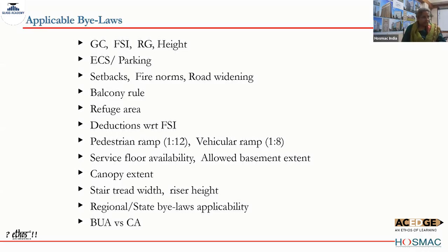But 3 meters is never good for a hospital because under the slab are, again, I would say this word, the nerves of the building, okay? Electrical lines, plumbing lines, firefighting, air conditioning ducting, and also the medical gas pipelines. All these are like a network under every slab. If a hospital has 3 slabs or 20 slabs, every slab will have these networks.